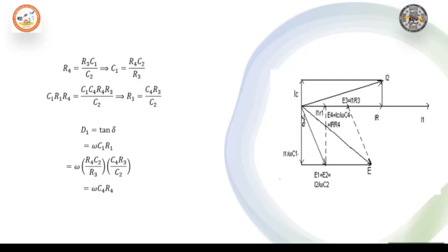A different frequency can be used, but a correction should be made by multiplying the C4 dial reading by the ratio of the two frequencies. Similarly, if the resistance ratio is maintained at a fixed value, the dial of C3 can be graduated in terms of direct readings of C1.